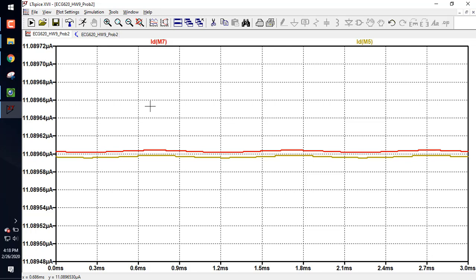Well, it's when you're down in picoamps, that's in the simulation noise. So, I mean, you got to question what the results are. Everybody got that? That's not hand waving, right? You can't realistically simulate something to infinite precision. And if you simulate it to 1 picoamp, which is what we're seeing here, that's 1/1 billionth of an amp, whatever 10 to the minus 12 is.